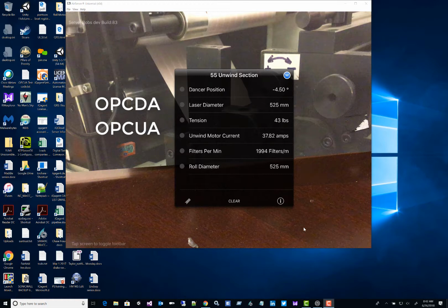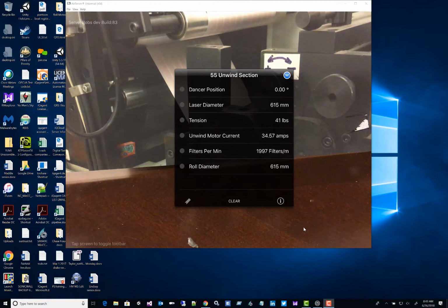We also use OPC-UA, which is a newer version, which is easier to network and has security built in. We much prefer that. We can also get data over ODBC, Open Database Connectivity. So if you have data in production databases like SQL Server, Oracle, things like that, we can grab live data out of that and show it right when you scan the point of interest.